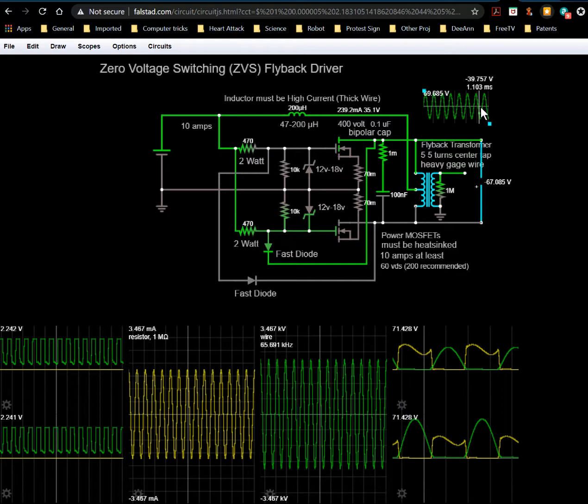So again, the transistor switches when this voltage is zero. It's a zero voltage switch. So this is the voltage that has to be zero to change the switch direction. Okay, but it does essentially reverse the capacitor when it happens. So even though this is a negative voltage versus a positive voltage, it still is looked at like a positive voltage from the other transistor, because now instead of this lead being referenced to ground through this transistor, now this lead is referenced to ground through that transistor, because they switch, basically, is what's happening.